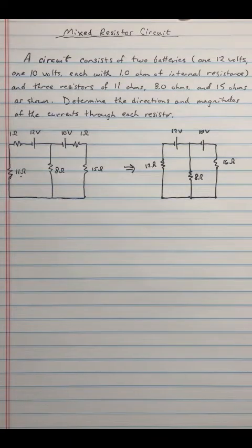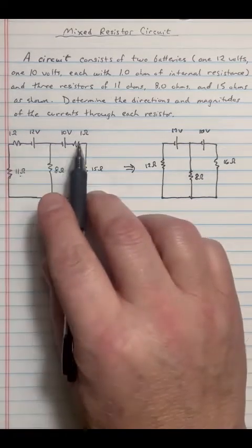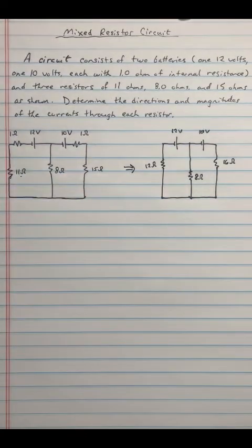Why then go to all the trouble of drawing it with the internal resistances? Well, first off, that might be something you don't actually know at the beginning of a problem. An internal resistance, if you do some of this work in detail, depends not just on the battery itself, but actually how much current is flowing through it. So we're already making an approximation. And second, we do need to see that this is an actual thing. Remember that actual real devices like real batteries or real power supplies do have internal resistance, and so we would need to account for that in practical problems.